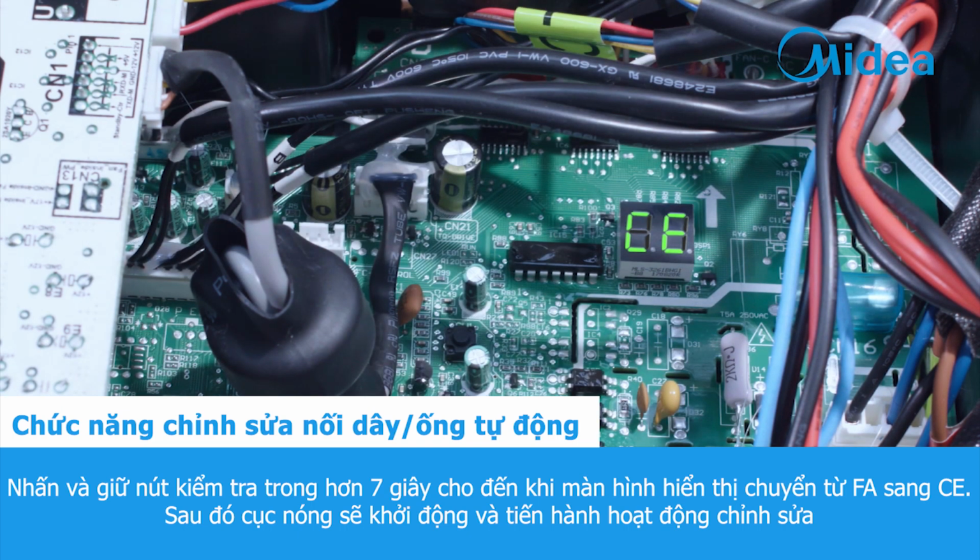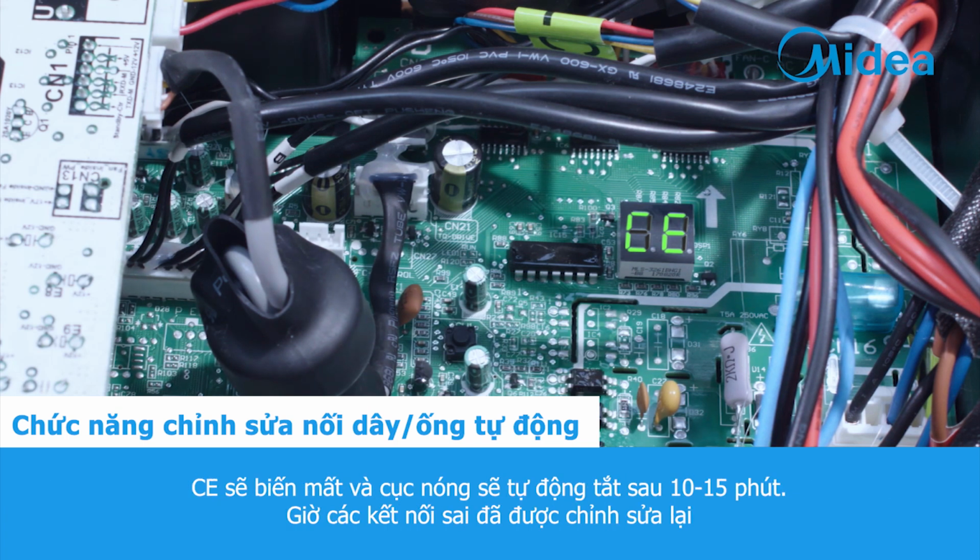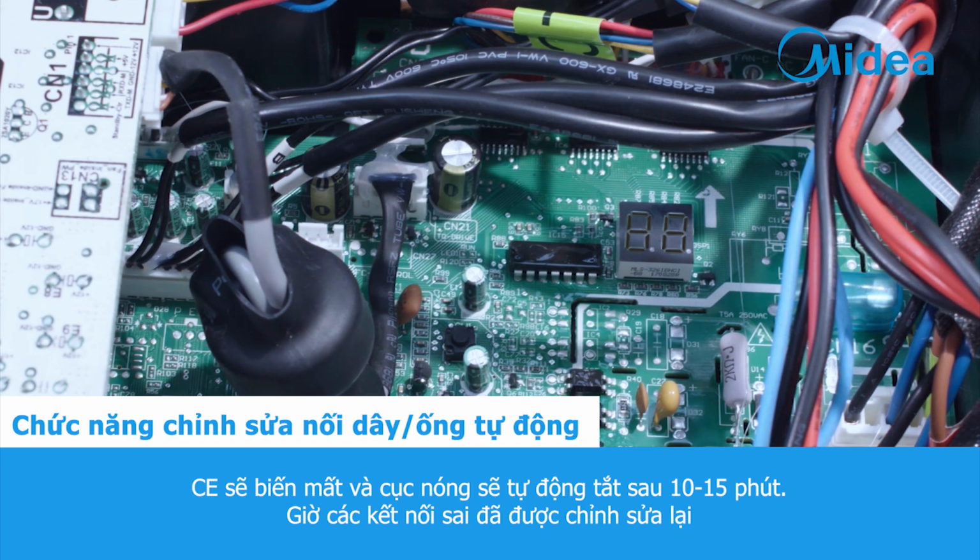Then, the outdoor unit will start and execute the correction operation. CE will disappear and the outdoor unit will be off automatically in 10 to 15 minutes. Now, the wrong connections have been corrected.